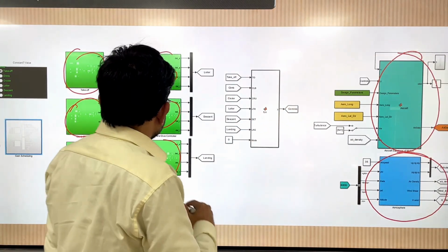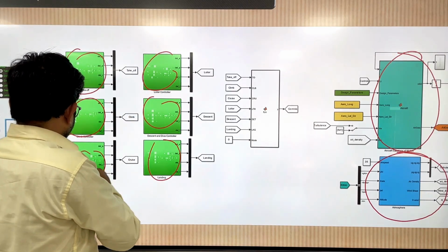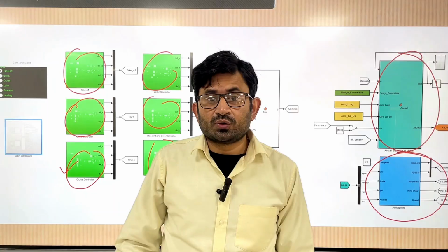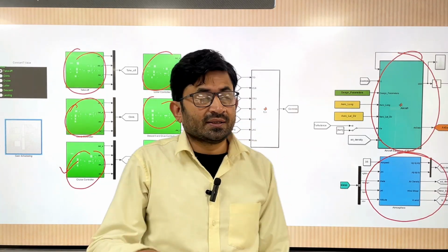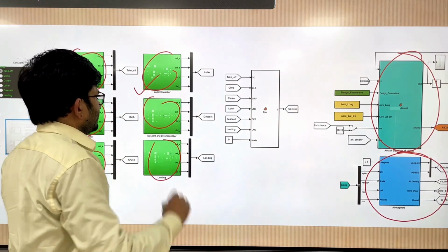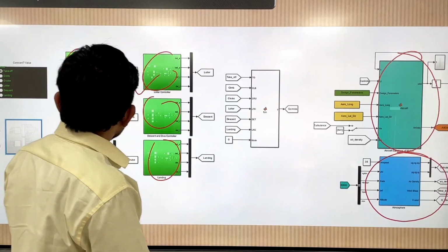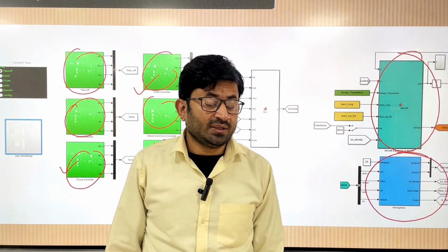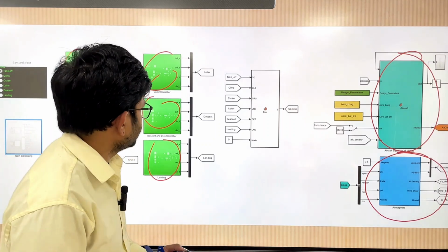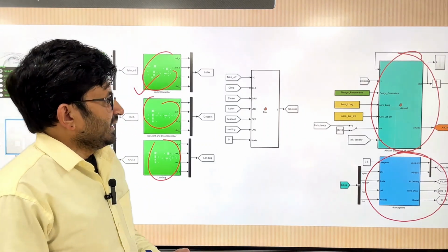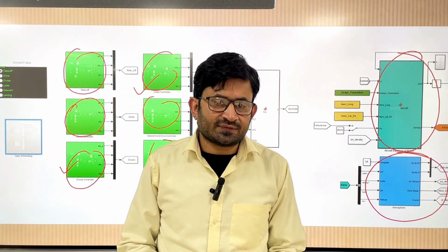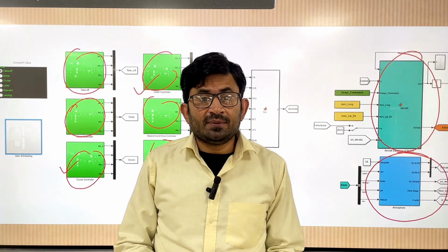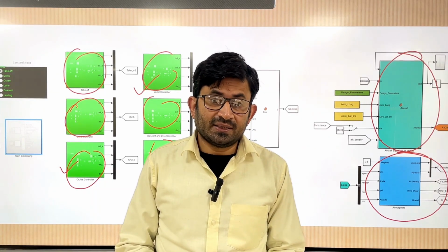So this is basically the cruise controller. And in loiter I have already discussed how to hold the bank, how to hold the heading. Let's say that becomes the loiter one. So likewise we have covered all the control loops. If you have any doubts, please ask, I will try to explain. But in that we have considered the transfer functions like q by delta e, p by delta a, beta by delta r.